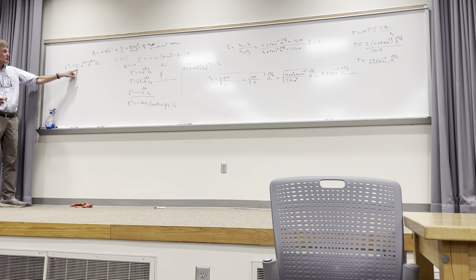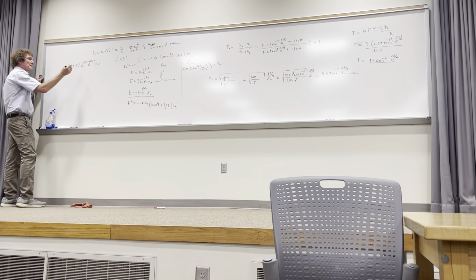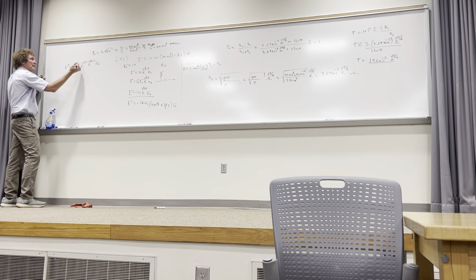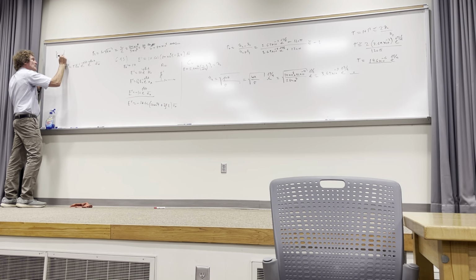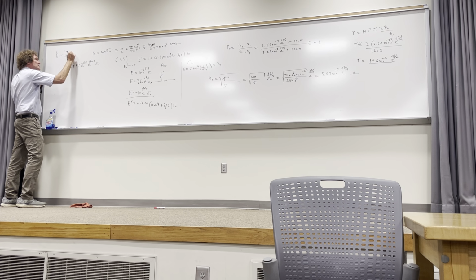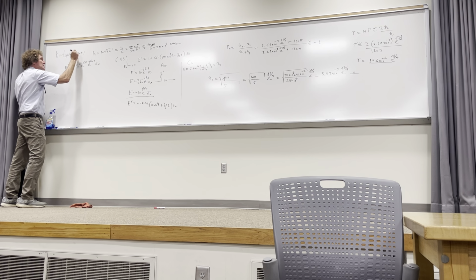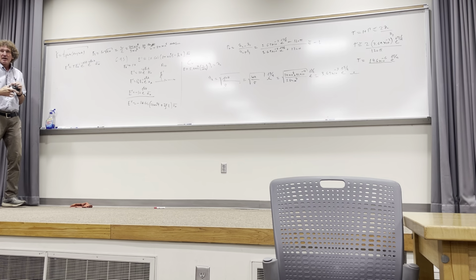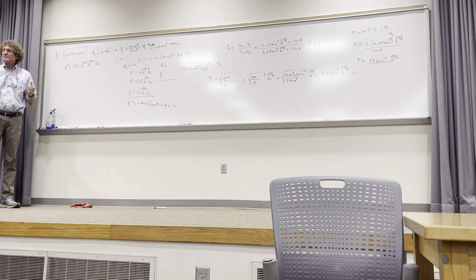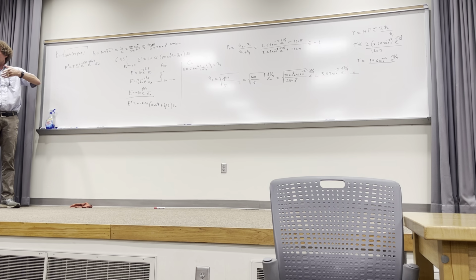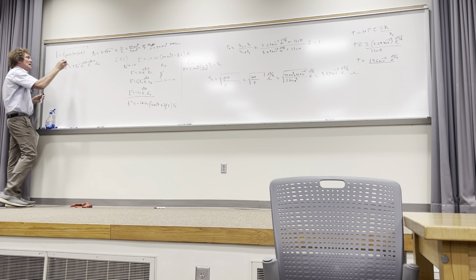If you wanted the formal equation, we could get gamma, I mean alpha and beta, pardon me, which would be the same because it's a very good conductor. We could say gamma is equal to the square root of j omega mu times sigma plus j omega epsilon in the copper, right? Do you follow me on that? Now, what approximation would I do here? The omega epsilon is so small compared to sigma, right? Copper sigma is 5.8 times 10 to the 7.